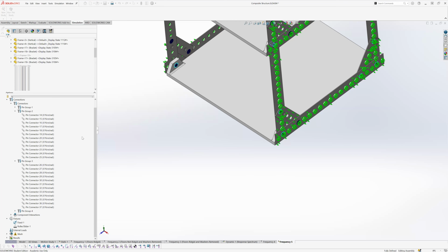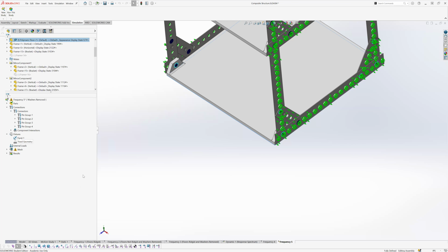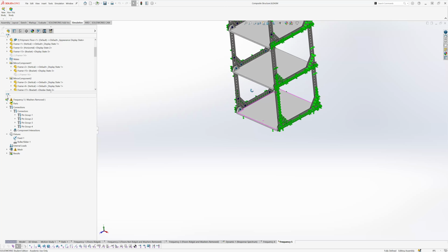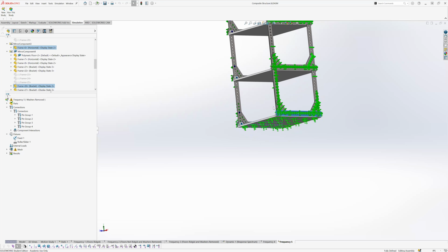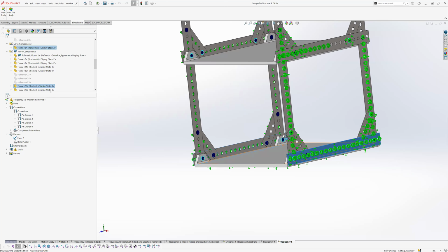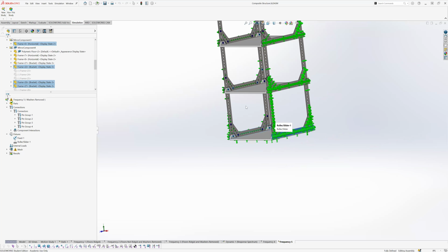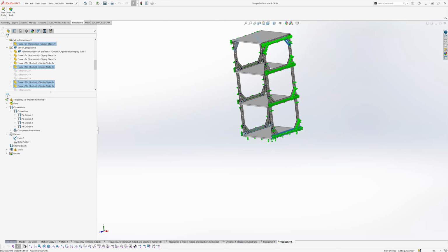So let me get out of here. All right, click here. Let me see if I can go down here. We'll try to collapse these. Okay, so we've got that. Now our pin constraints are fixed. Our roller and fixed constraints are still good. We can still see the symbols. Obviously, those have nothing to do with the washer. So we should be good now to rerun our study.